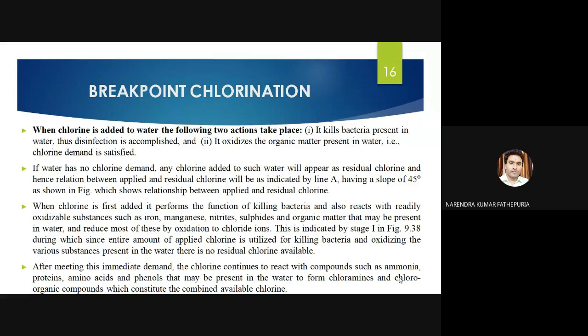When chlorine is added to the water, the following two actions take place. It kills the bacteria present in the water. Thus, the disinfection is accomplished. Number second, it oxidizes the organic matter present in the water, like chlorine demand is satisfied. If water has no chlorine demand, any chlorine added to such water will appear as a residual chlorine.